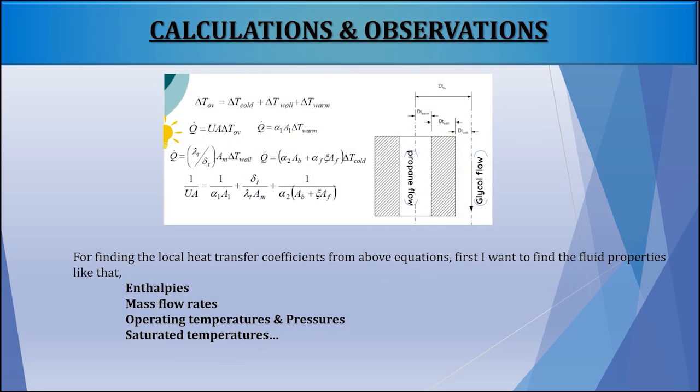In this slide, I detail how I approached the calculations to find local heat transfer coefficients. I first needed accurate fluid properties including enthalpies, mass flow rates, operating temperatures and pressures, and saturated temperatures.